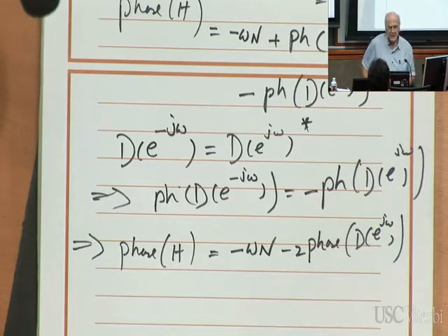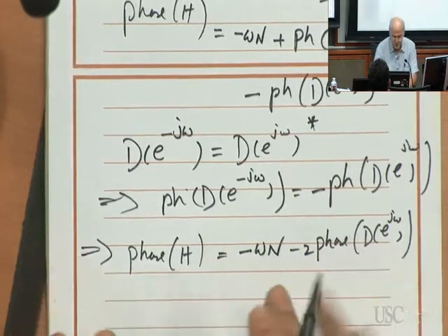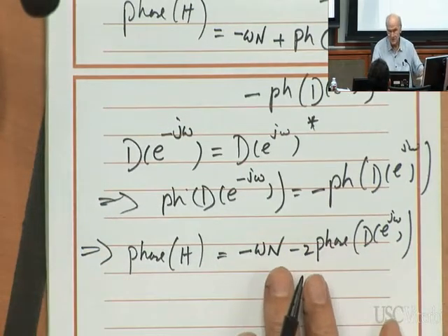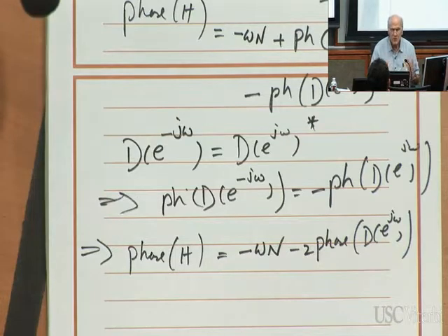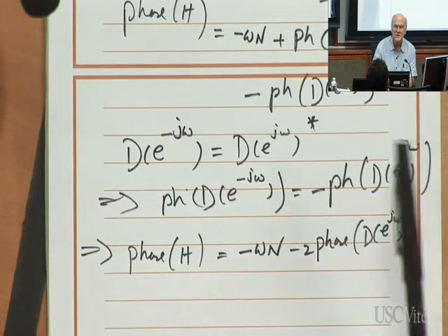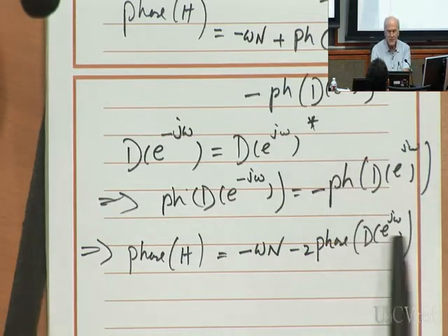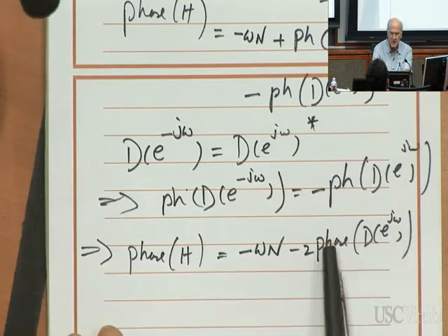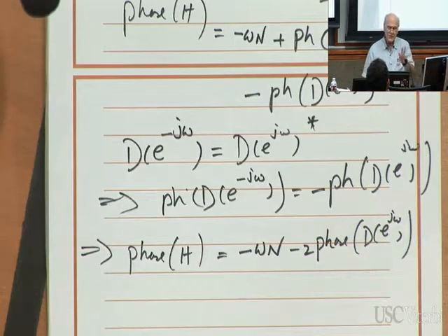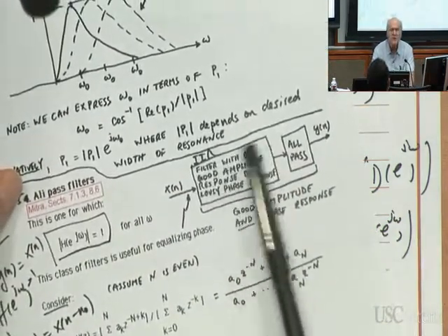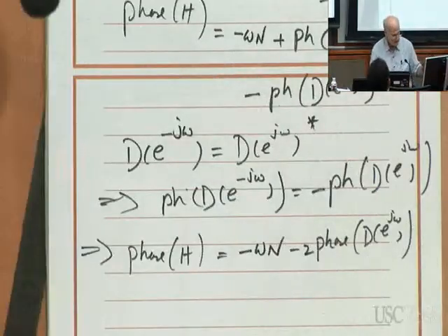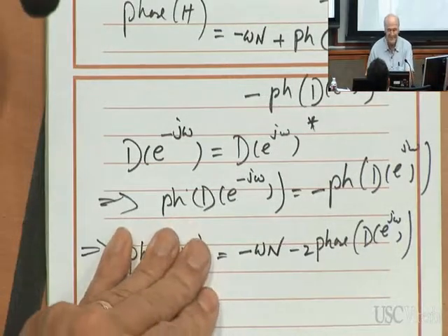What they do is they attempt to make the phase minus the phase of this bandpass filter to be as small as possible using a least squares technique. So they can vary the coefficients to change the phase response here, and they try to change that in a way that minimizes the phase distortion here between this bandpass filter. So anyway, that's good exercise.